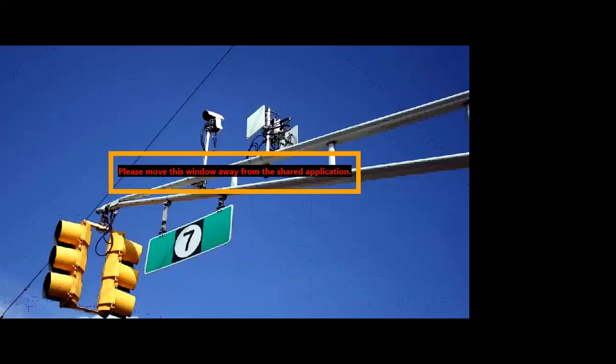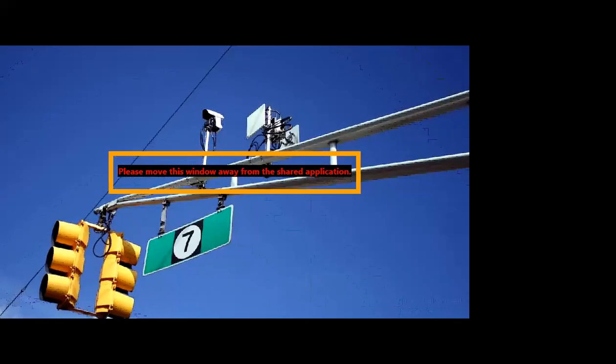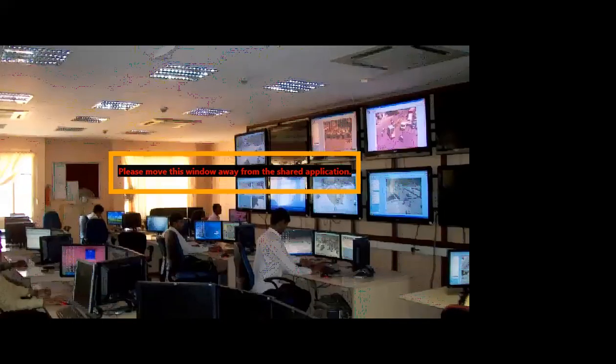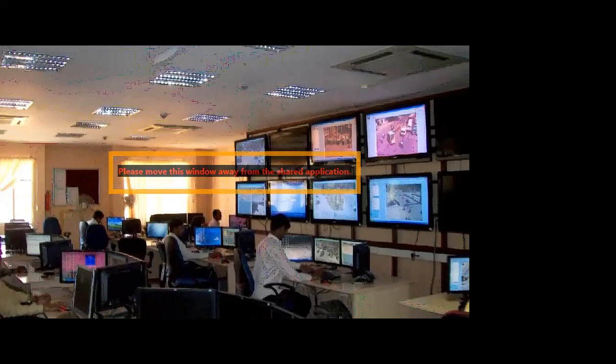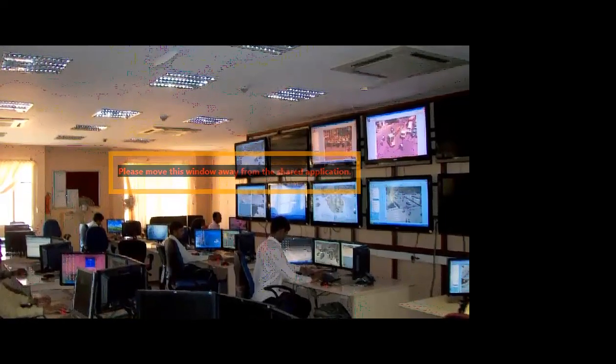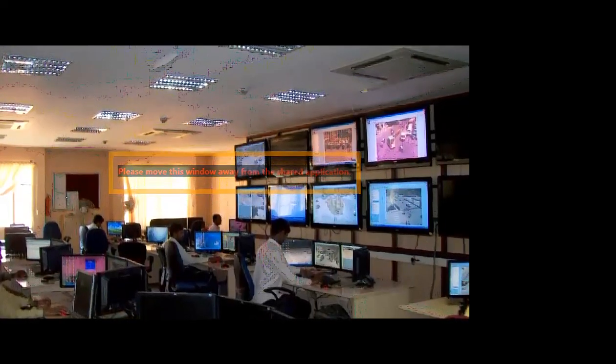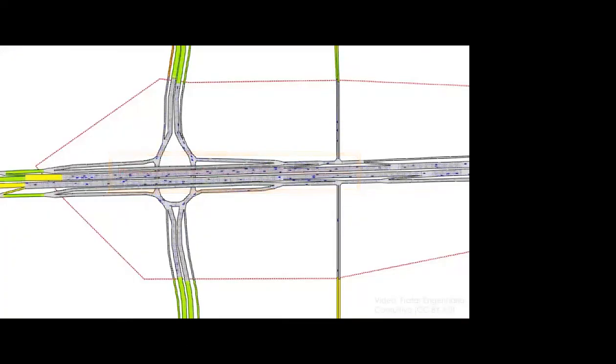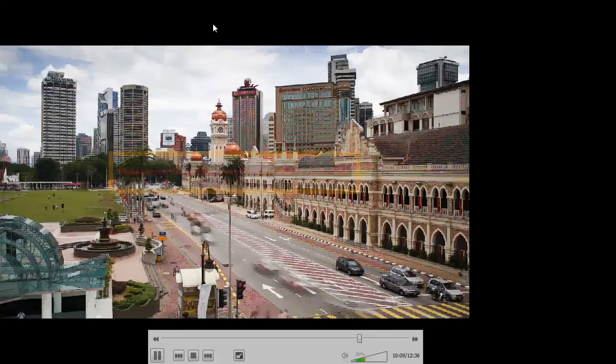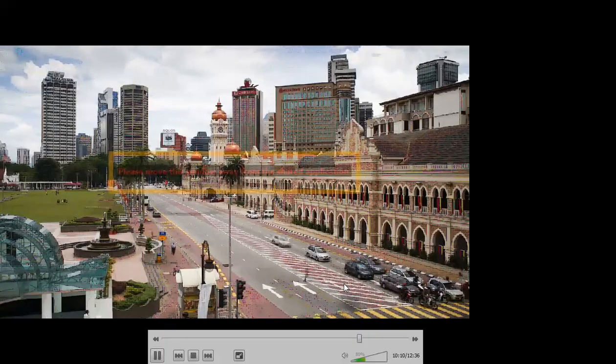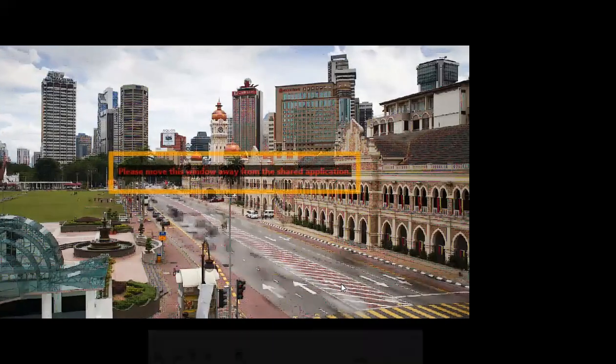The obvious next step in efficiency is coordination of most or all the signals within a traffic network. This is the job of adaptive signal control technologies, or ASCT. In adaptive systems, rather than individual groups of lights, all the information from detectors is fed into a centralized system that can use advanced algorithms like machine learning to optimize traffic flow throughout the city. These type of systems can dramatically reduce congestion, but they're only just starting to be implemented in major urban areas.